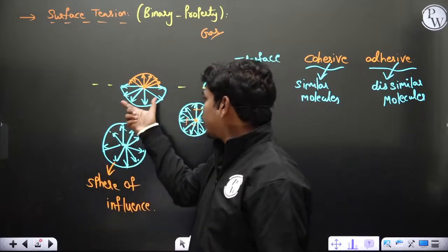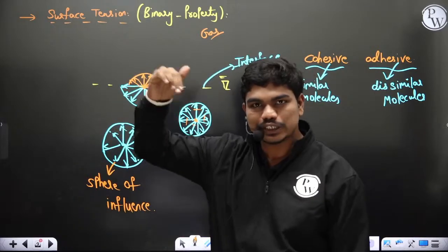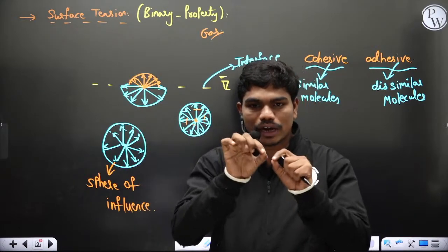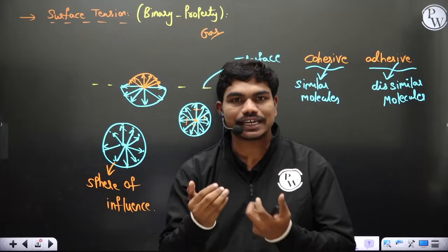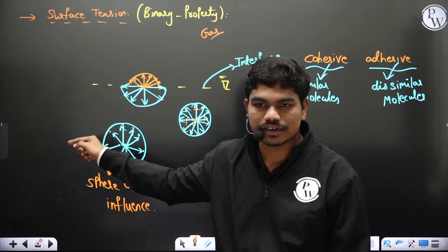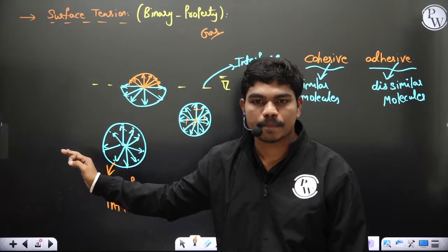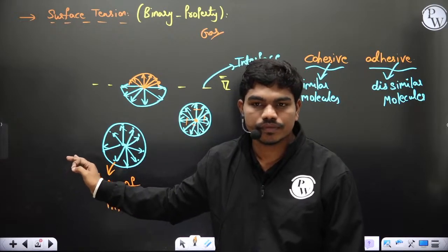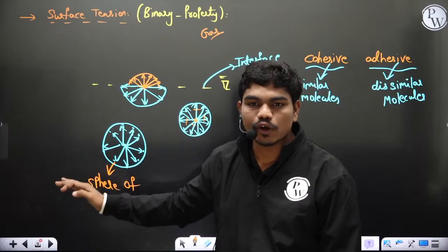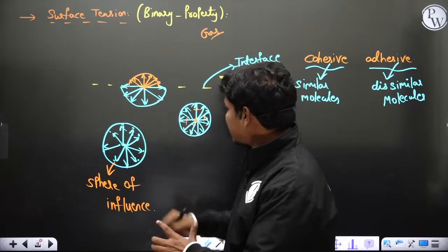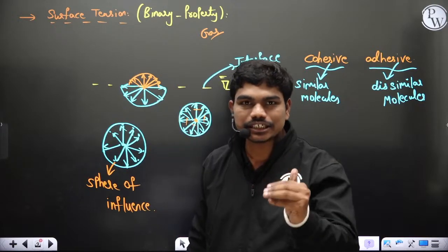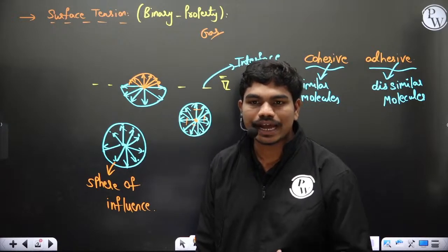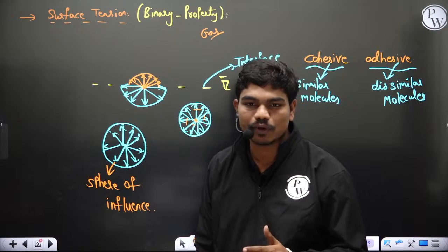Clearly you can see, because downward there is a high cohesion, and on the top at the interface, due to the other fluid, the cohesion or the adhesion forces are slightly weak in this case, yes or no? Which means the molecules on the surface are actually subjected to a certain imbalance between cohesion and adhesion, yes or no? Can you feel this? So please type in the chat box. Can you all see clearly that this molecule which is at this particular interface is not balanced in terms of mechanical equilibrium? Correct? Can you all accept this? Everyone should type in the chat box.